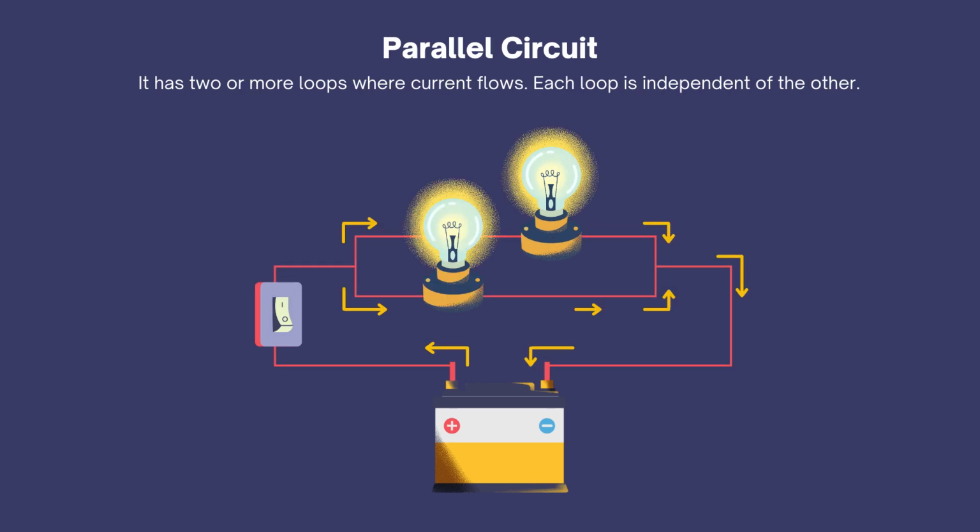In a parallel connection, all positive terminals are connected together, and all negative terminals are connected together. This configuration keeps the voltage the same as a single cell, but increases the total current capacity. For instance, two 1.5 volt cells in parallel still provide 1.5 volts, but can deliver twice the current.